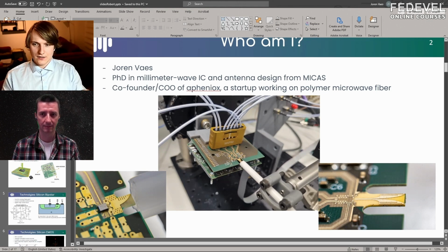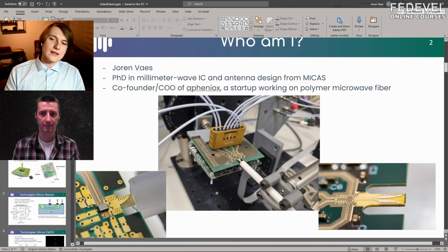Imagine you're assembling a car module, and because of a defective machine, 1 in 100 chips has this ESD event. They all still work when they leave the factory, but 3 years later, 1 in 10 of these cars is failing because these chips are dying, right? And that's why it's very critical to really understand this design. And it's why you have companies whose only job is to design these blocks for chips.